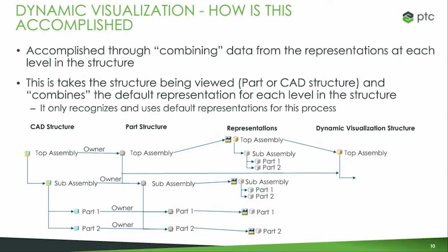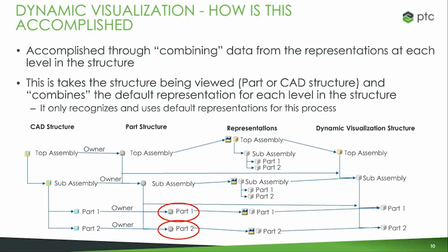It will then go to the next level and read the root node of the representation tied to the subassembly. In this case, this is where the importance of that weld geometry came in. It's going to have to read the weld geometry from the subassembly's representation. That introduces some restrictions or constraints in how you visualize this, which I'll get into a little later in the presentation as things you might want to consider. It then goes on and builds out all of the rest of the content based on those representations.